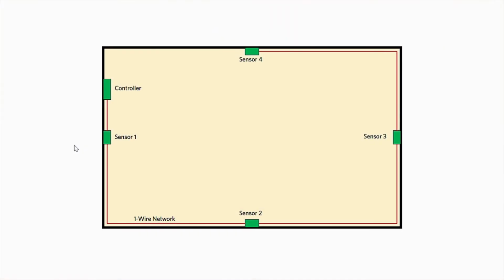located. For example, let's say I want to measure temperature at multiple points around the perimeter of a room. A simple solution would be to connect one-wire temperature sensors like the DS18B20 to a single one-wire bus that runs around the room. After setting up the sensors, I would need to manually index the sensors, matching each ROM ID with a location in the room. That might be okay for a single room, but setting up multiple rooms would quickly become tiresome and time-consuming.